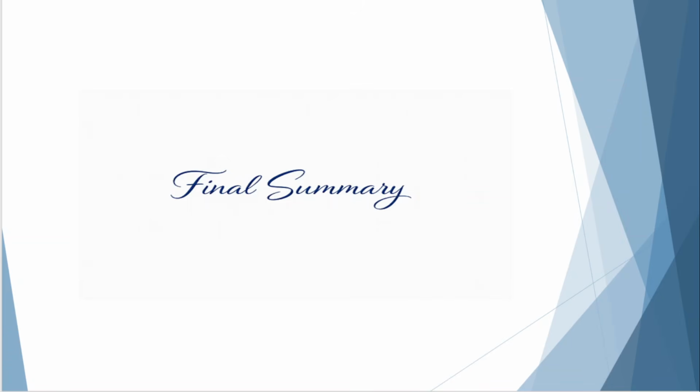Let's summarize the key points we've discussed throughout this presentation. A reciprocating pump produces pulsating flow because the piston continuously accelerates and decelerates during every revolution. As the piston changes its velocity, the liquid inside the suction and discharge pipes must also accelerate and decelerate. Since the liquid possesses mass and inertia, additional pressure is required to produce this acceleration. This additional pressure is known as the acceleration head.